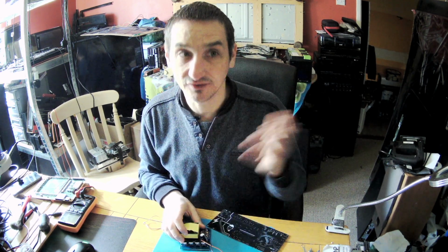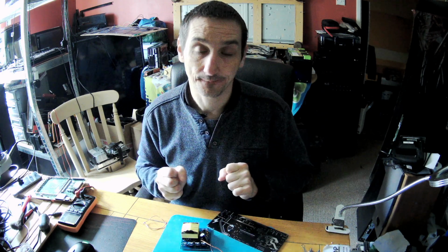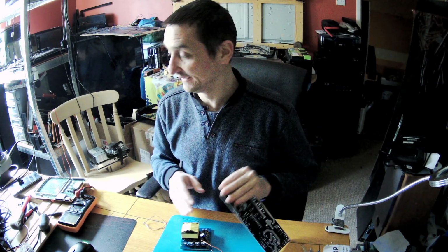Those MOSFETs are cheap, and RDS on, you see, heat dissipation, all of it is just not there. If we could replace it with something else, we should gain something back, so it should heat a bit less and it should be more efficient, I'd say. How much we will, again, I'm not a designer, I just fix electronics, I don't know. Probably I can ask, probably I can calculate it, yes.